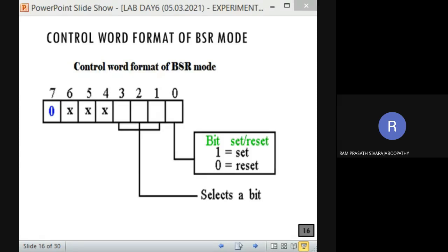Correct? Okay. Say for example, இந்த 3 bit எதுக்காக யூஸ் ஆகுது அப்படின்னு பாத்தீங்கன்னா, which port bit we are going to set or reset. Port bit select பண்ண போறோம். Select a port bit. Say for example, PC5 அப்படின்னா என்ன வரணும் இங்க? If I say PC5, what must be the 3 bits? Very good, Anthony Surya. 101. If I say PC7 அப்படின்னு சொன்னா என்ன வரணும்? Yes, very good, Danya. 111.